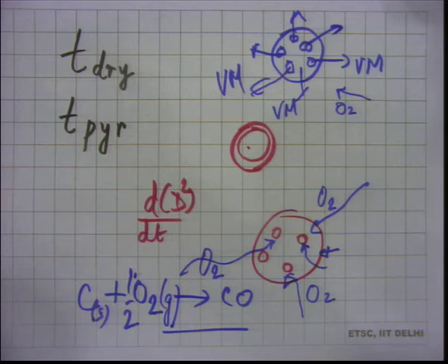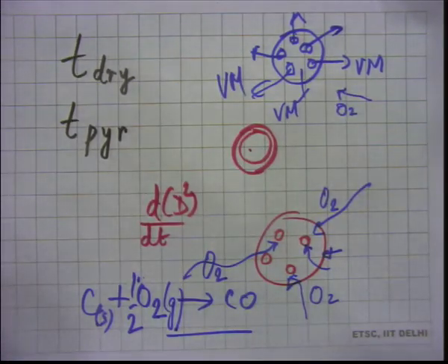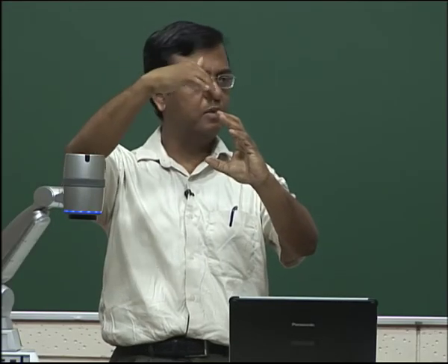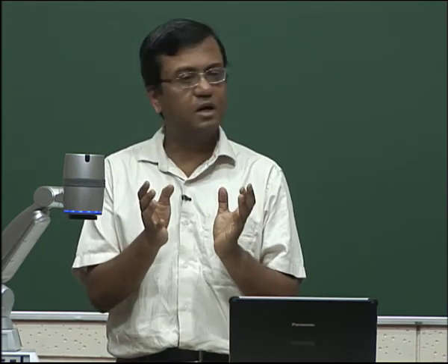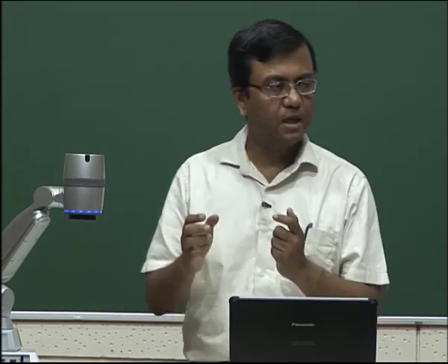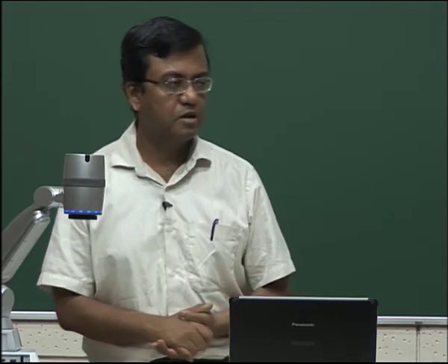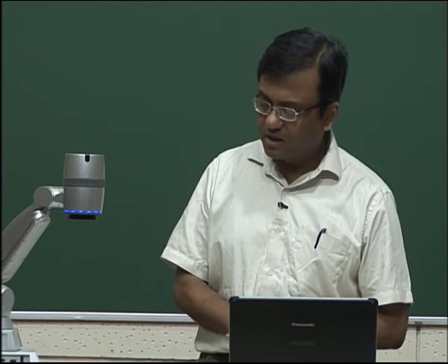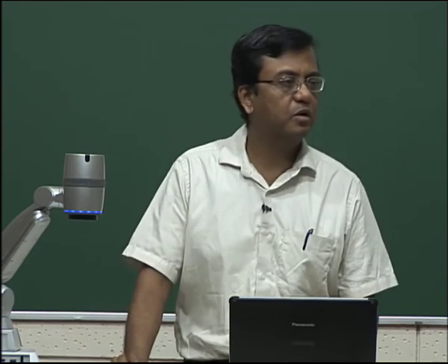When the volatile matter is coming out and porosity is getting established, it's a little difficult for the oxygen to come and attack the carbon, because there is competition. Once the volatile matter flow stops or has reduced considerably, the oxygen finds it easier to attack the solid of the char. Then this sort of reaction starts: carbon plus oxygen giving you carbon monoxide, let's say.